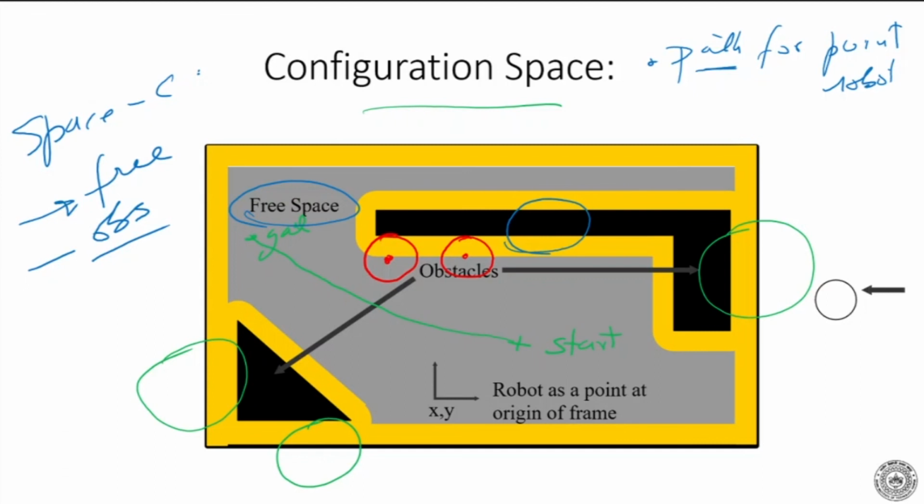That's not very difficult because geometrically you're moving a point. So if you know the coordinates of this point, or you know the vertices, you know the coordinates here, right? So you can just check that the point should not go inside anywhere there. That is the meaning of the robot going inside an obstacle. So the paths are basically planned in Cartesian space, and this is how we come to the Cartesian space. So today we will stop here and then proceed.